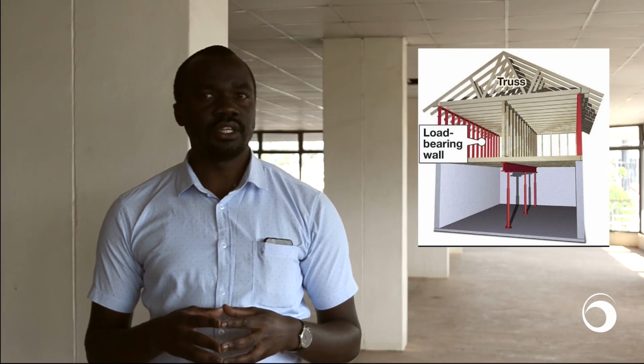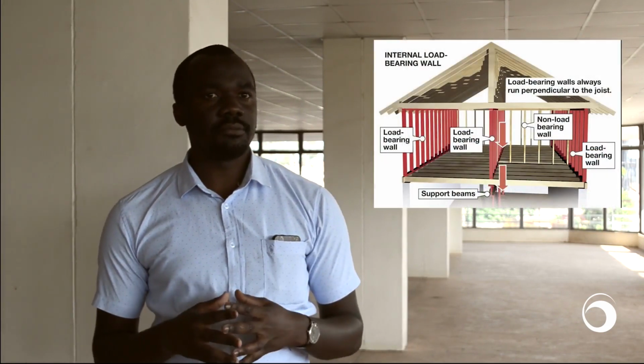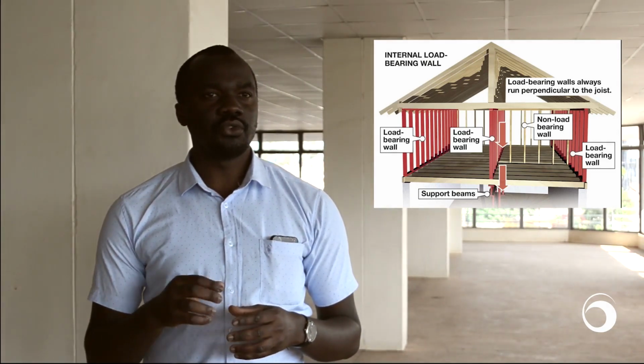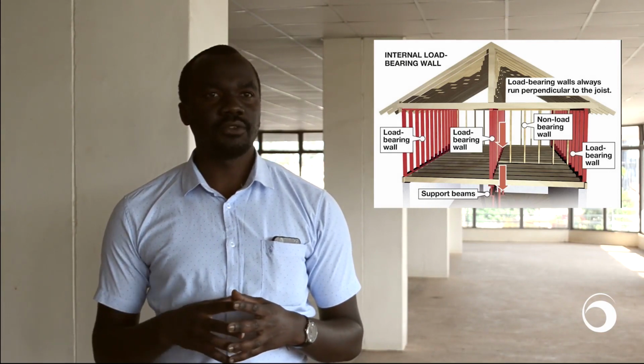Ideally, why you would be doing the integrity assessment is to assess whether some walls are load-bearing or not. Now, load-bearing walls, you'd have to take more care with them, not to remove the structural part or the load-bearing part of the wall, not remove so much of it. If it's not load-bearing, you'd be worried more about the ceilings if it's already built or the floors above.